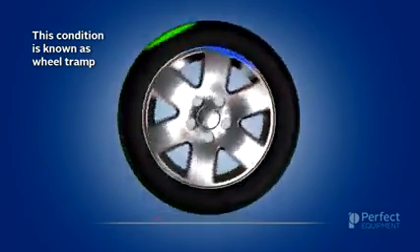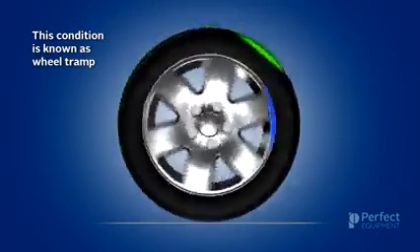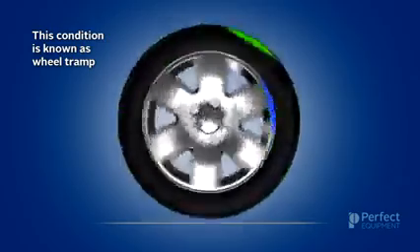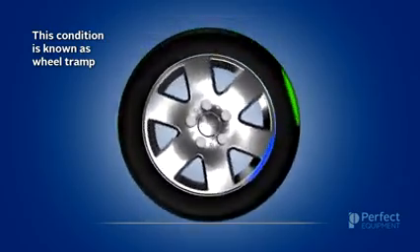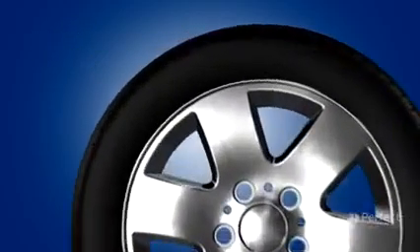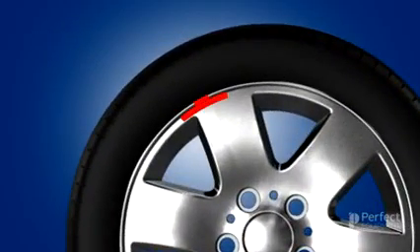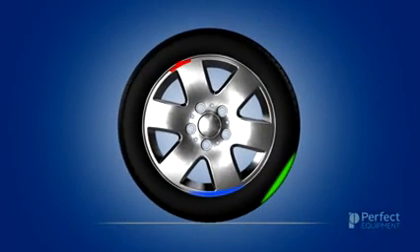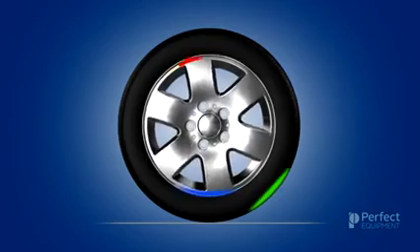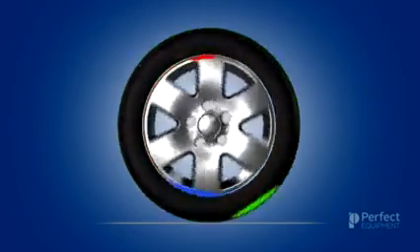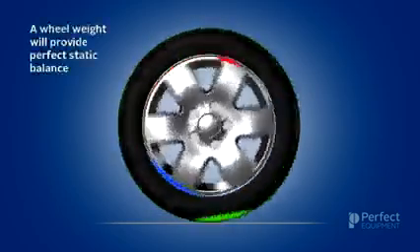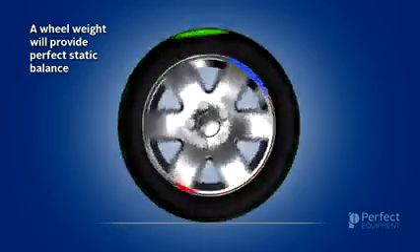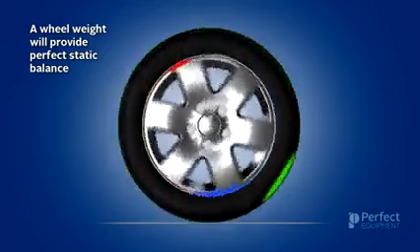If left unchecked, wheel tramp will produce uneven wear patterns on the tires and cause a severe up and down vibration while driving at highway speeds. To correct this problem, a wheel weight of some type must be applied to the light spot, or the opposite side of the imbalance, in order to equal out the weight distribution of the assembly. With the wheel weight applied, the static imbalance is corrected, and the wheel assembly can now spin with perfect balance.